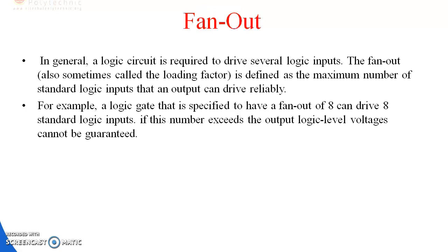Then next is fan-out. In general, a logic circuit is required to drive several logic inputs. The fan-out, also sometimes called the loading factor, is defined as the maximum number of standard logic inputs that an output can drive reliably.